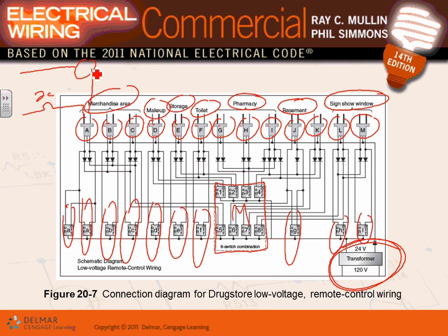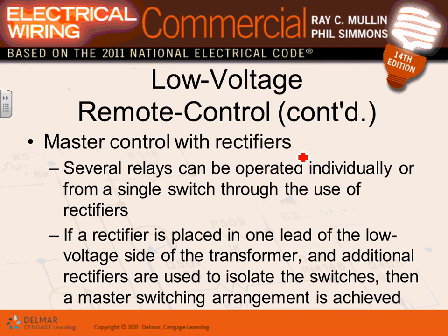This panel, what did they say, 19 relays or whatever, how many relays? Oh yeah, these are the relays. All these relays, all these are diodes. Can you guys see, remember diodes? Did you do electronics? You haven't done electronics with us, some of you did. Diodes, guys, they control the flow, they're valves. They control the flow of current. I want the current to go in this direction, but not coming back. To control the flow of the current in a low voltage 24 volt system, they use diodes. You're going to see them in a second here.